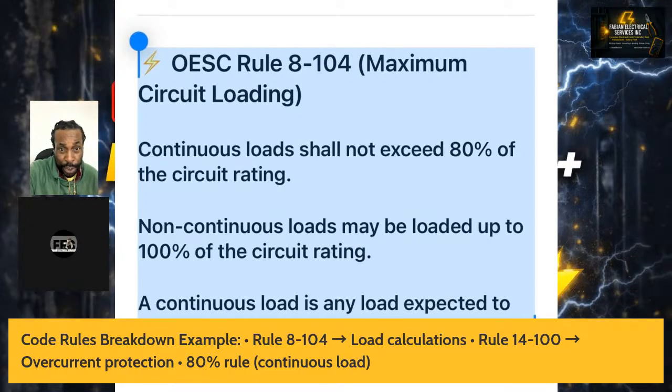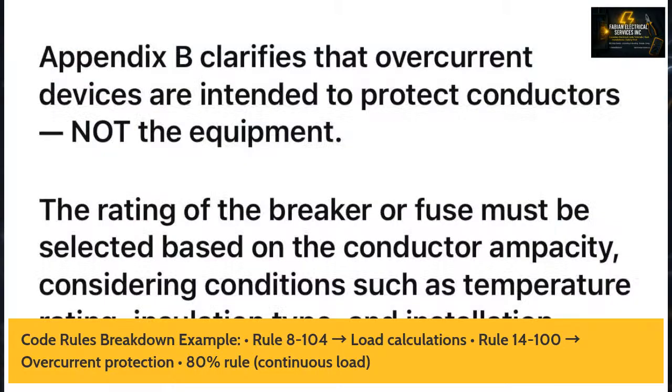So that is continuous load. Also, I'm going to pull up the other one here, another rule. I'm not sure if you are seeing that properly. This is basically talking about how the overcurrent device is intended to protect conductors, not the equipment. So again, your overcurrent device...